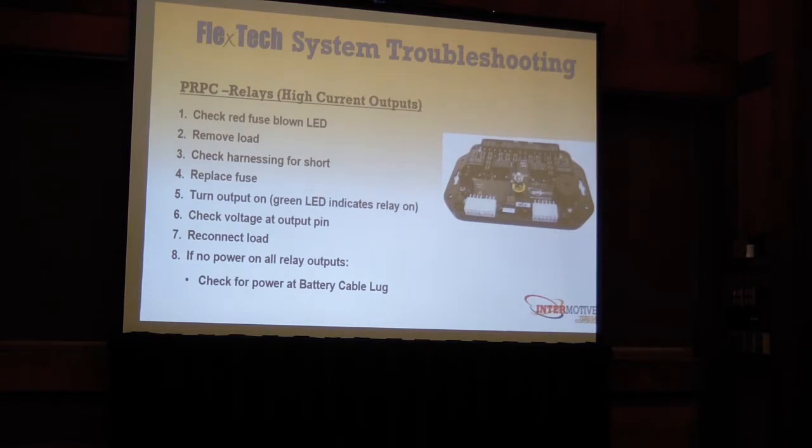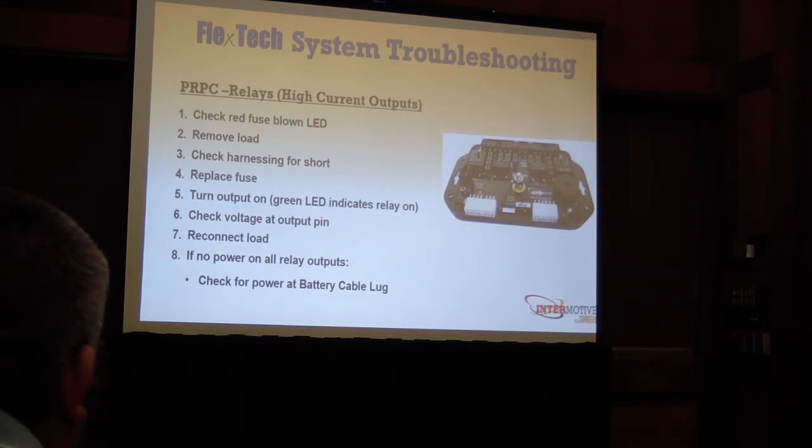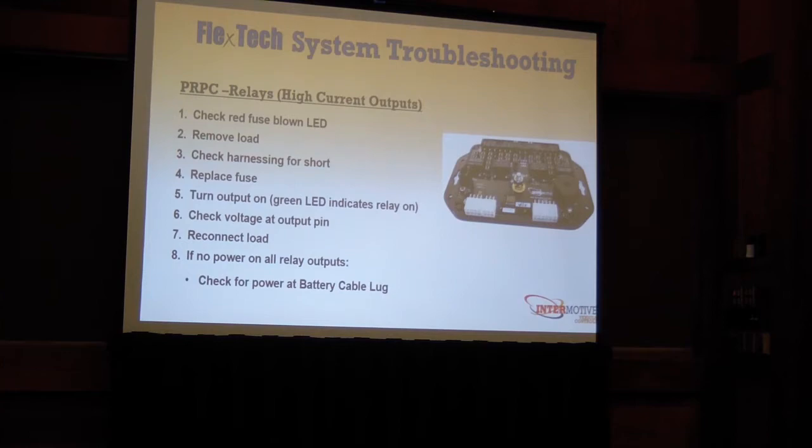3 and 6, you can see there's 2 vertical fuse holders there. Those are not meant to be placed at the same time. It's a fuse stuff option to provide ground or 12 volts on the output pin. If you place both fuses, you're going to blow the fuses. You're connecting power to ground directly. So that allows you to provide a sinking or a sourcing output there.